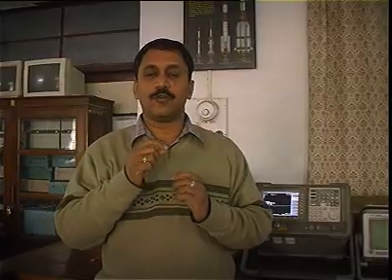What do I mean by saying that signal can get distorted? If I calculate the Fourier transform of a signal, I am representing the signal in frequency domain as capital X of omega. I can write this capital X of omega as equal to modulus of X of omega multiplied by a phase factor. Now when I say the signal is getting distorted, the amplitude can get distorted, that is the magnitude can change, or the phase can change.